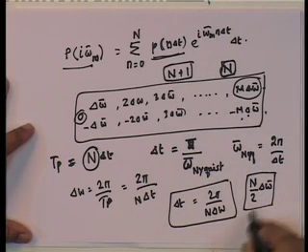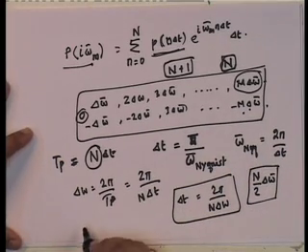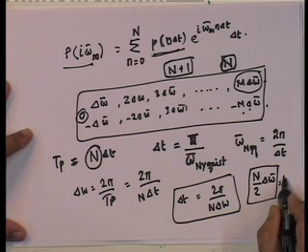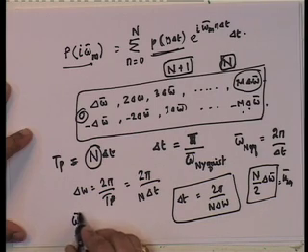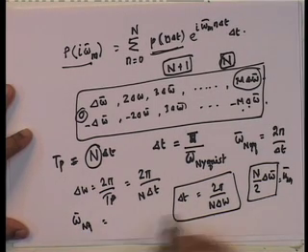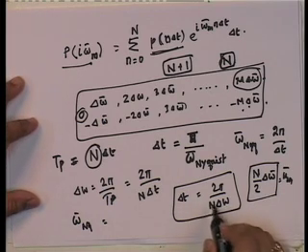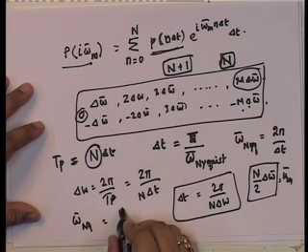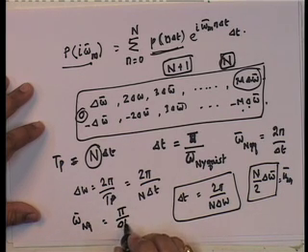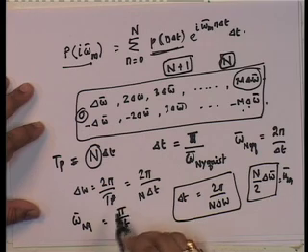So, if you just substitute that in here, this is the largest frequency, this is the Nyquist omega bar. If you really look at it, omega bar Nyquist, therefore, substituting this, n delta omega bar becomes 2 pi n delta t upon 2. So, this becomes pi upon delta t.